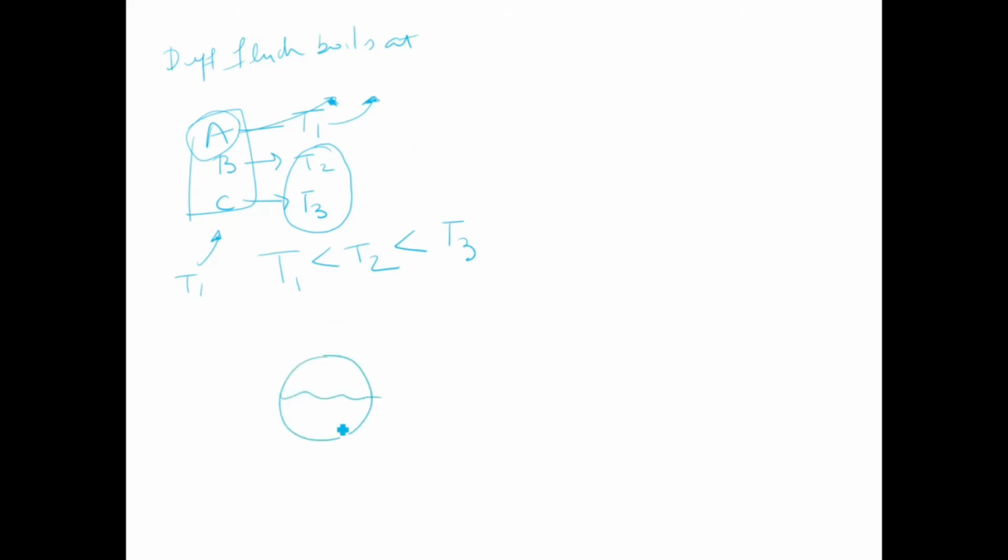Normally we have some fluid mixture, and based on the difference in boiling point, we manage to separate one component as a vapor phase, and the remaining components, which boil at a higher temperature, we collect in the liquid phase. This is something we can call volatility. It depends on the volatility of the fluid. So volatility is inversely proportional to the boiling point.